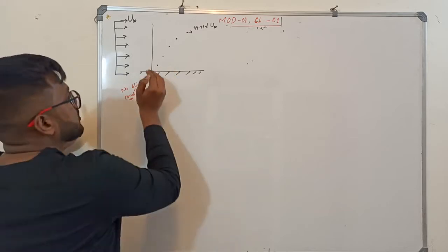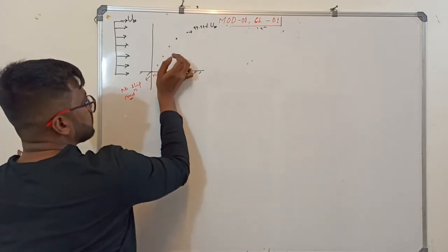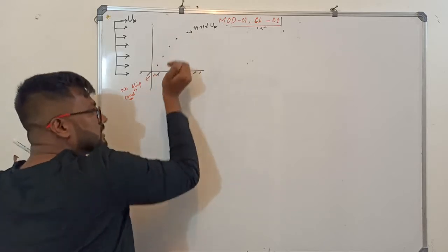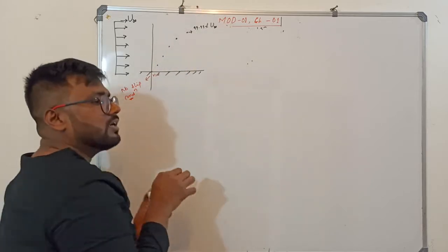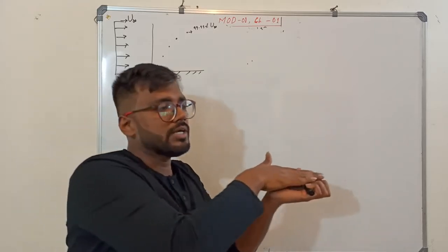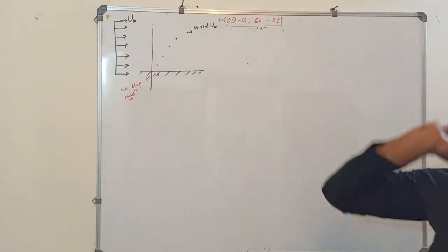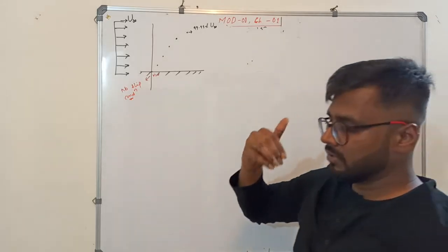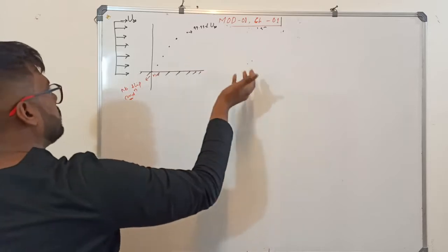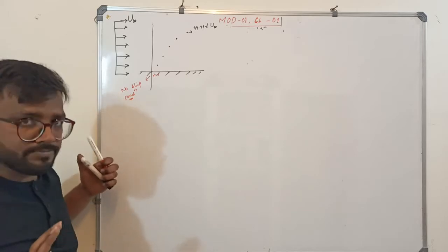As soon as it touches the first layer which touches the surface, its velocity becomes 0. Then this one resists the next one, because of the property of viscosity. अब ये वाला इसको resist करेगा. The third one will resist the fourth one, which again will resist the fifth one. So there will be a resistance of motion between adjacent fluid particles as the fluid is moving. There will be a point where the velocity of the fluid will be almost equal to the free stream velocity. We will study the details of this in the boundary layer.